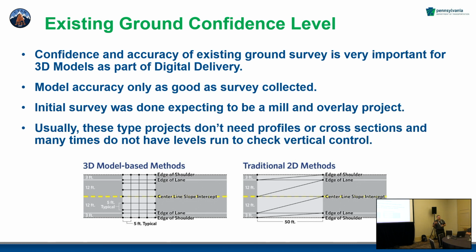You think about a survey out there, a lot of times, traditionally today, you might be doing 25-foot intervals, 50-foot intervals, something like that. Well, you miss everything in between. So your model's not catching all that data in between those places. So we said, okay, let's densify this more, let's get more shots. So we said, let's do LiDAR for hard surfaces, traditional for outside, and combine those.